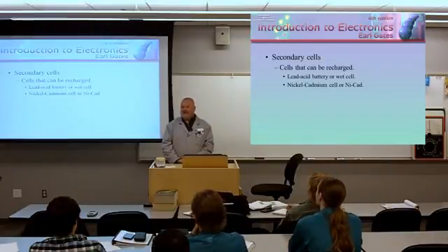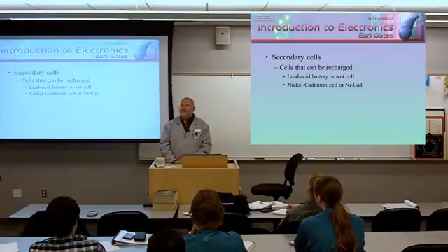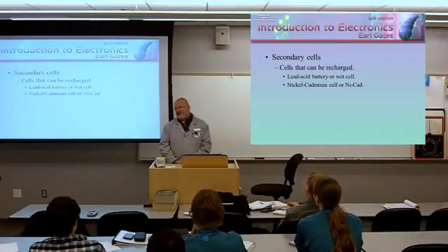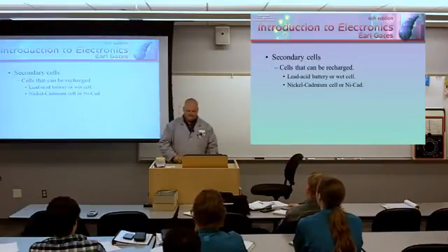I cut it open and it was just standard NiCad batteries. Usually it doesn't have the label on it, but the sizes were the same. Then I went to Harbor Freight Tools and bought nickel metal hydride rechargeable cells, put the pack back together, soldered it up, good to go. So in some cases you could do that.